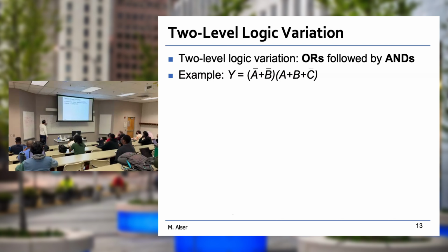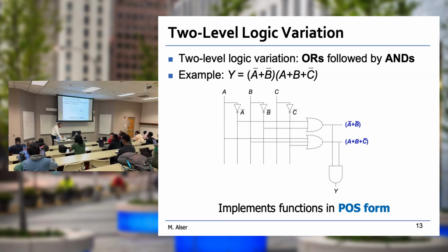No. You can remove the wire, yeah, but not the C, because C we need it for C bar. The wire is always the cheapest element in the circuit. You could add as many as you want. The only thing, it might affect the resistance. But normally this wire is very thin, so you don't increase the resistance, okay? So you could delete the blue one, but it's really not impacting. What we're worried about is the gates themselves. The gate is something huge. For example, this NOT is 2 transistors. So it's taking space, okay? Plus taking power, taking energy, and so on. All right?